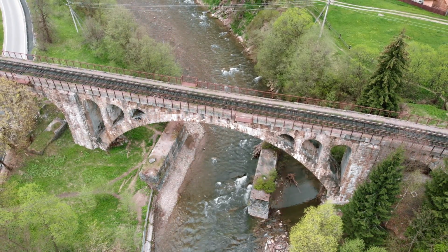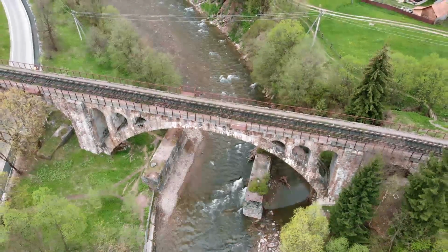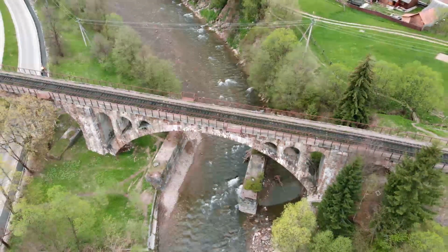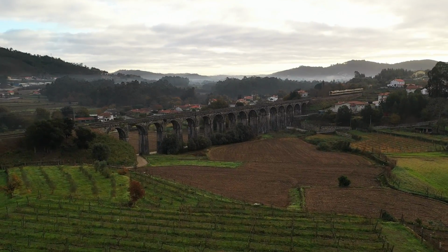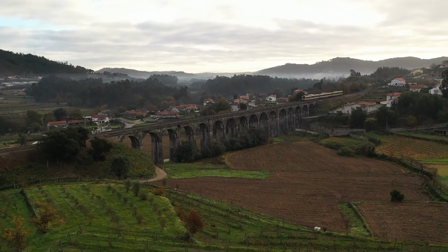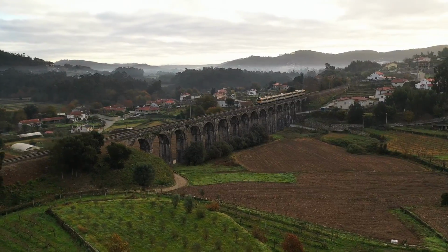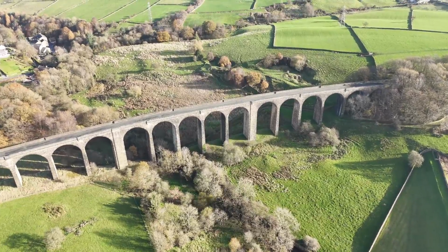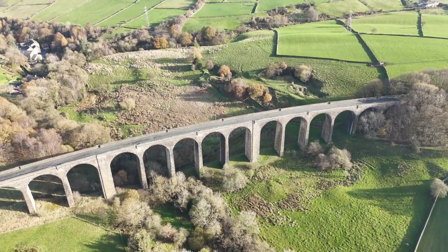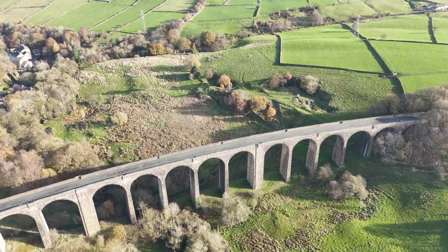So each bridge type brings its own risks and things to remember. Let's run them back. Brick arches. Check your drainage pathways. Where is the water getting away from the bridge? Monitor the structural movement and remember the tie bars that might be buried in the ballast or even deeper. Watch for long-term settlement trends and movement within the structure. Look out for cracks in the arch barrel or the parapet walls.